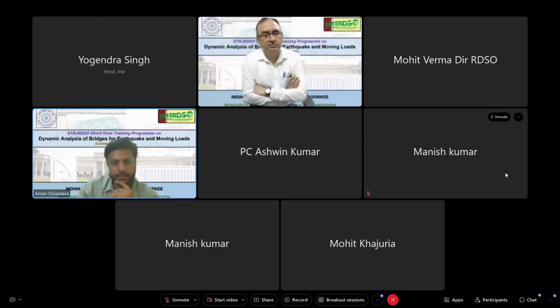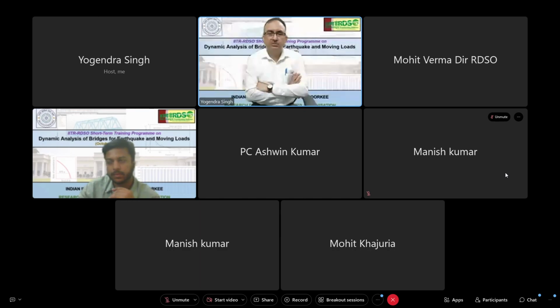Okay, sir. Mr. Jay is asking, to get a mass participation factor of greater than 90%, we can also go for Ritz vector eigenvalue analysis rather than direct time. So thank you for providing this information. I should have also included that. Sometimes the eigenvectors which we are getting in usual modal analysis, these eigenmodes cannot provide us 90% mass participation, but Ritz vectors can provide. In that case, we can go for Ritz vectors. That is allowed.